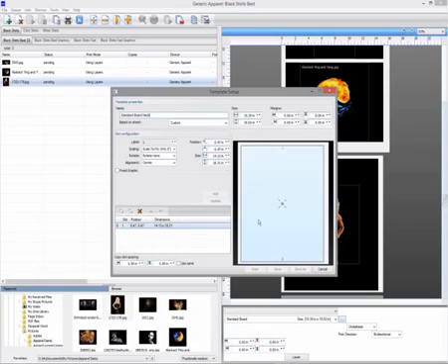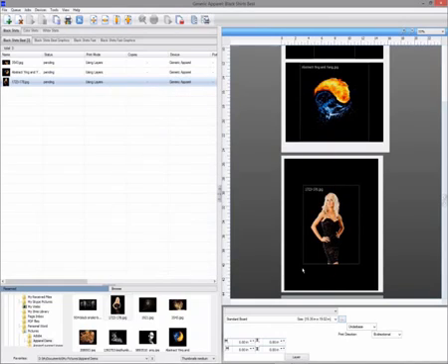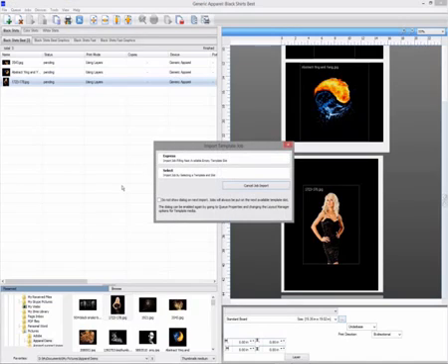The slots are the print areas, and I can click on the slots in either list view or preview to select it. Then for this slot, change my alignment to top middle. Click Update to update the slot, and Save As to create my new template. If I import a graphic now to my new template, it will position the graphic at the top middle.